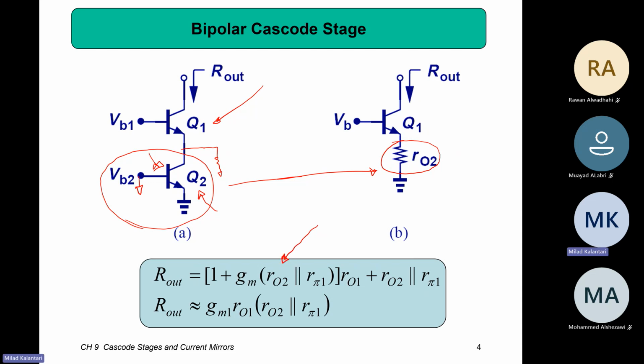But you can simplify it, right? This is the original equation. So how can we simplify it? We know that the R out of the device is considered as a big resistor. Remember, R out was a big resistor compared to the r pi. So this can be simplified as just R out. And then the other side is just r pi, you can say, right?